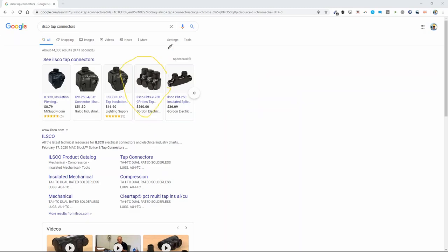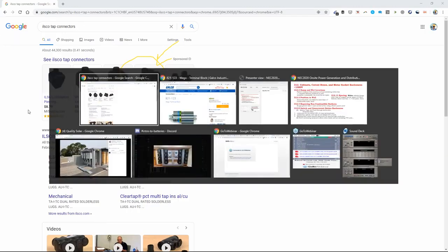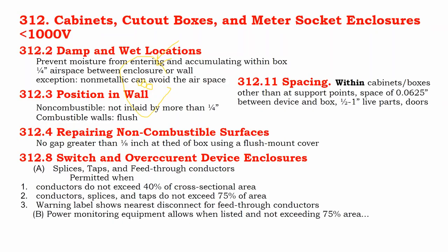These knuckles take up space. They're larger than the cabling itself, and so what we see in National Electric Code is rules governing how large the box needs to be in order for you to not just pass the conductors through the box, but also to do work on them. And then also, the cross-sectional area of the entire box.